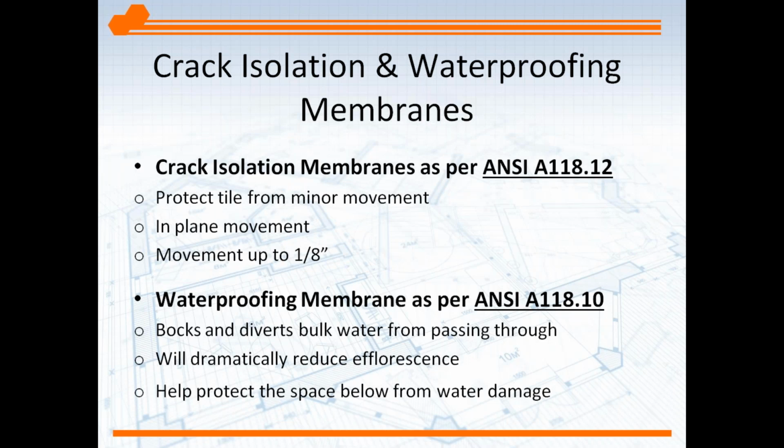Waterproofing membrane, the ANSI standard is A118.10. Now, what we expect out of a waterproof membrane is to block bulk water from passing through it. So we're talking about in showers, in bathroom situations, in water features, whether it be a fountain, in pools, areas like this, exterior, where you would use a waterproof membrane.